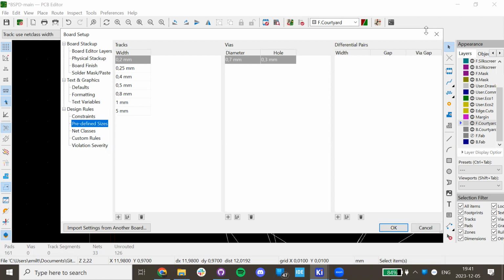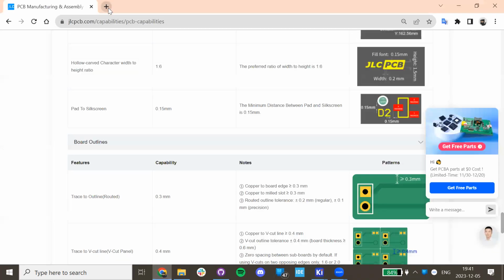And then, say we have our shutdown circuit. Currently it's fused at 3 amps. So you don't want your PCB to burn, you want the fuse to burn. So then you would have to dimension all your shutdown circuit traces to be for 3 amps. I'll just show you what that would look like here.